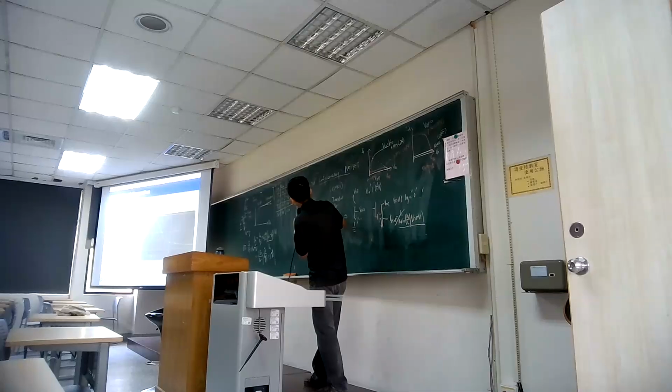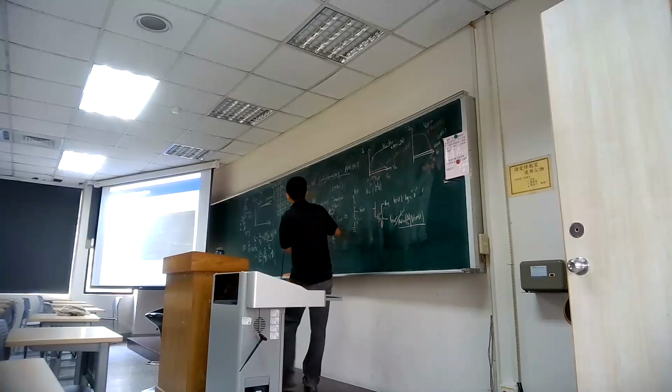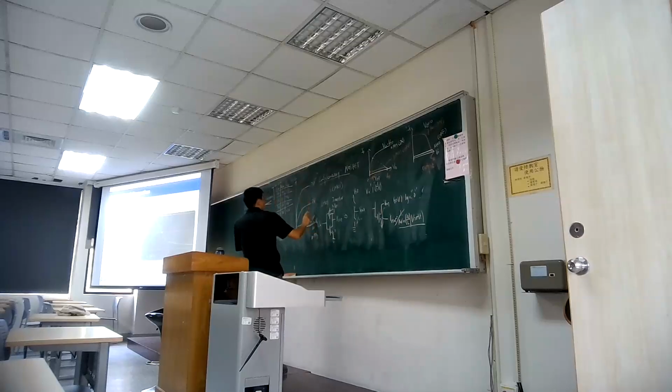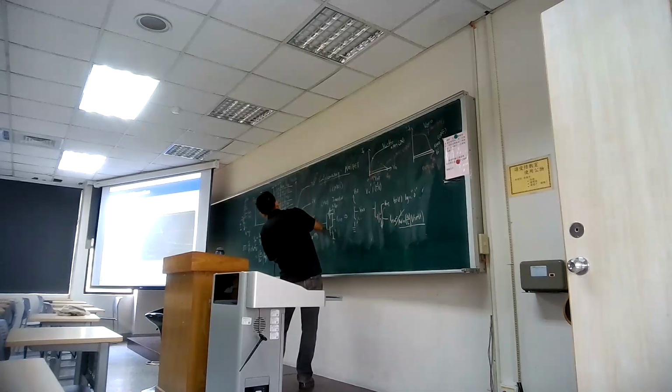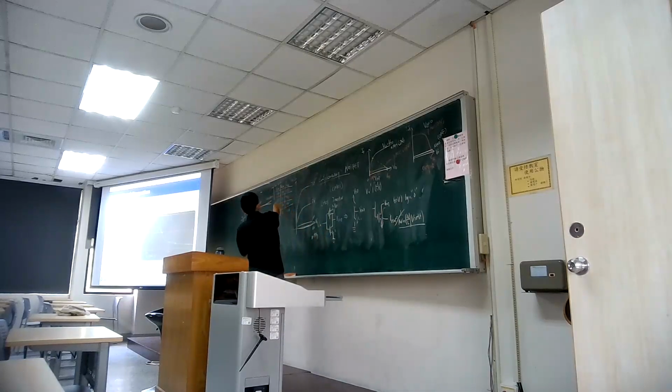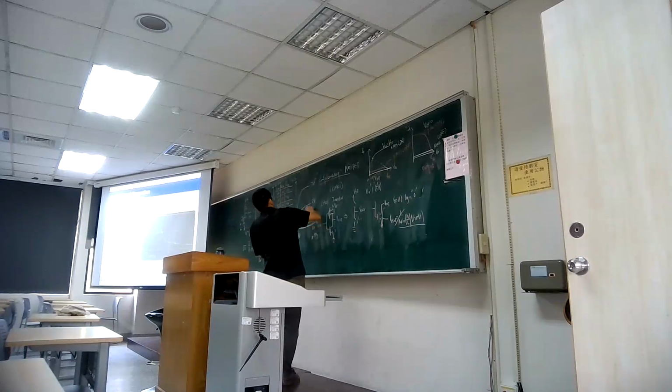So we notice that if you use 0 volt, the corresponding VGS will be minus 5 volt. It's just like you use 0 and then you use 5 volt here. The difference in VGS will be negative 5. For negative 5, that means you get really high voltage here for your PMOS.